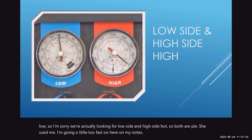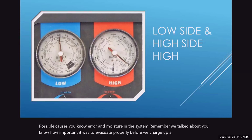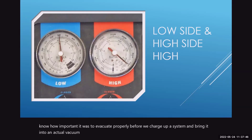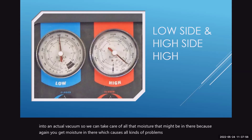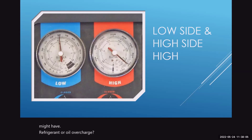Possible causes: air and moisture in the system. Remember, we talked about how important it was to evacuate properly before we charge up a system and bring it into an actual vacuum so we can take care of all that moisture that might be in there. Because if you get moisture in there, it causes all kinds of problems. Also with air, if we have air in the system, it can cause the pressures to go all over the place. And then we might have a refrigerant or oil overcharge, and that's a possibility.